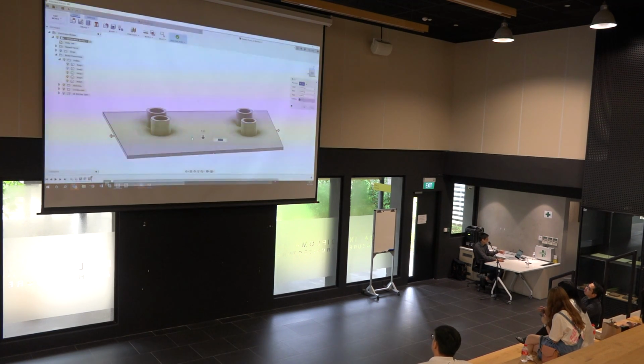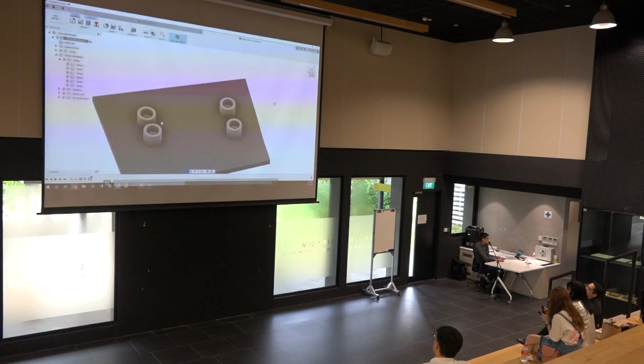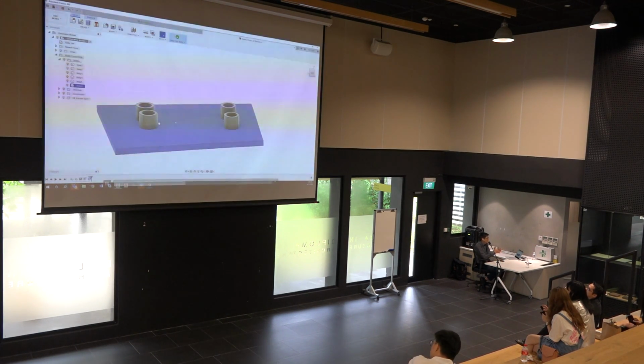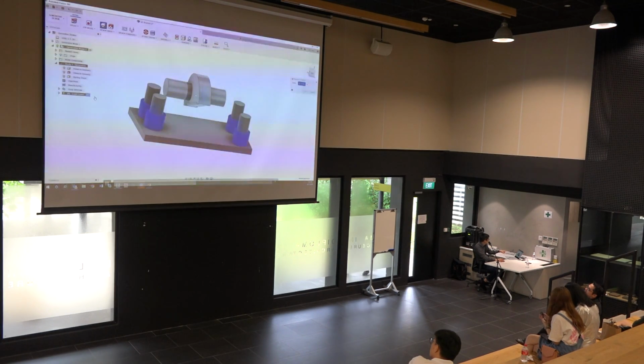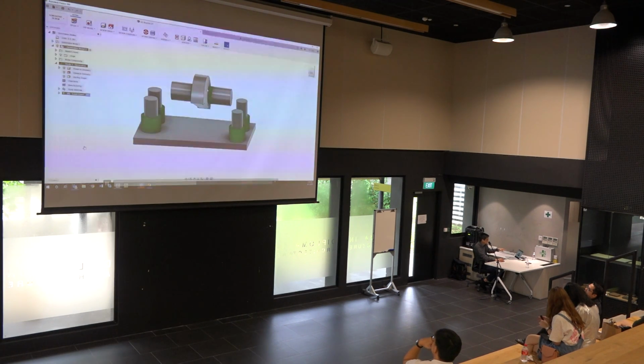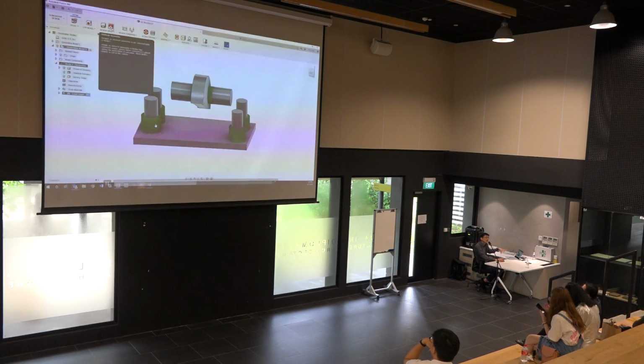And when you have the model, all these cylindrical shapes, you are selecting them as a preserved geometry. Now, think about it in the integrated Fusion 360 environment, because you can model them. You can drag and change the shape like what it did, right? Once you've done the modeling, you switch into the generative design function and select, okay, this shape is going to be my preserved geometry. Preserved geometry comes in one color, like green. When you generate the model, it will come with this green geometry. It will not change, right?